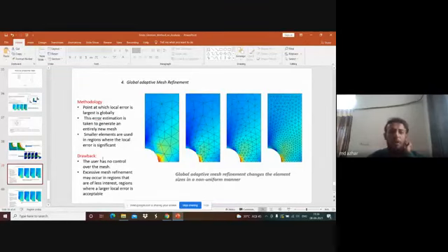However, the drawback is that the user has no control over the mesh. Once the calculation starts, mesh distortion will take place, and excessive mesh refinement may occur in a region of less interest, whereas in the region where there is a larger local error, the error becomes unacceptable.